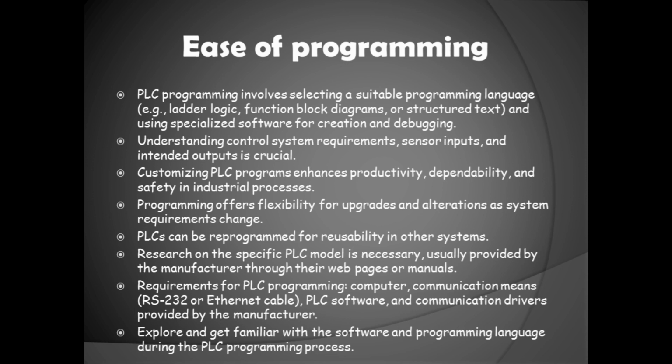To program a PLC, you need to do some research on the PLC you're working with. Usually, the manufacturer provides you with the information you need on their web pages or in the manual of the PLC. However, some common things you need are a computer, means of communication, usually an RS-232 or Ethernet cable, PLC software, and the PLC communication drivers, which both are provided by the manufacturer. And from there, you can explore and get familiar with the software and the programming language you're using.